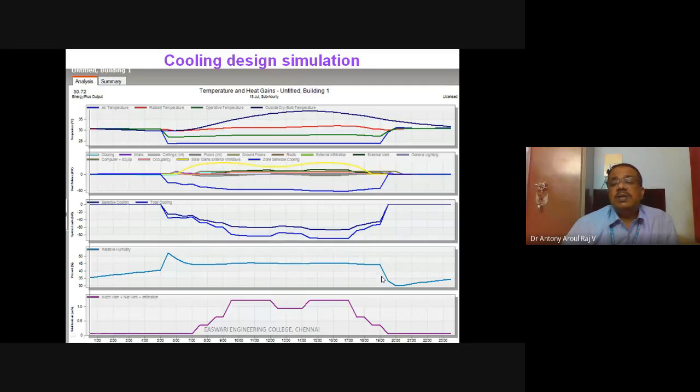At nighttime, general condensation will be there. Because of condensation, the water droplets from the atmosphere or the building will settle on the surface of, for example, a car or any equipment. Because of that, the relative humidity of the ambient will go down because moisture is separated. In simple terms, think of dew point temperature. During night time, the temperature of surfaces such as metallic surfaces, like the car body and car glass, goes below the dew point temperature. So the humidity from the atmosphere settles on these cold surfaces, the moisture gets separated, and the air becomes dry.